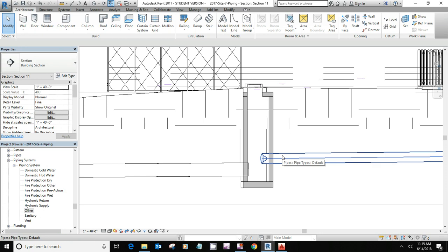those pipes. Okay, and usually the way they build these things is they'll dig the hole, of course, and the pipes are there, and then they'll pour a concrete pad on the bottom, and then they'll put formwork in, and then pour a concrete wall till they get up above where the pipes go, and then they can set round or square, most of them are round, segments down on top of it to get up to the top.